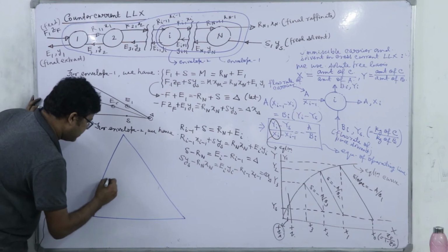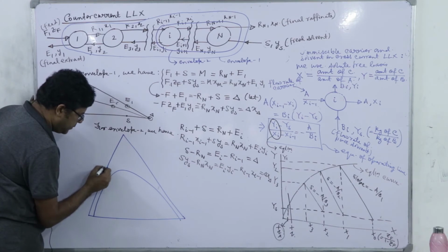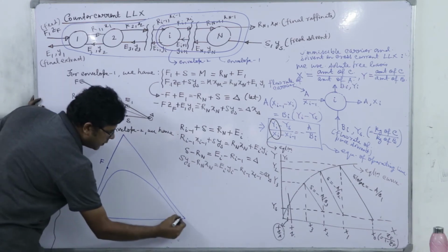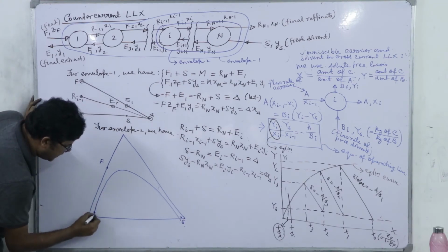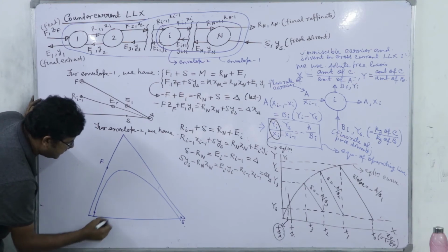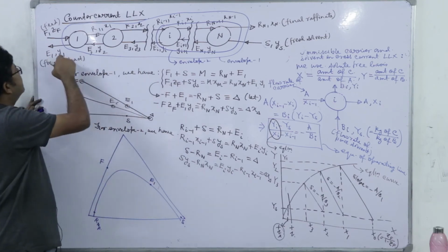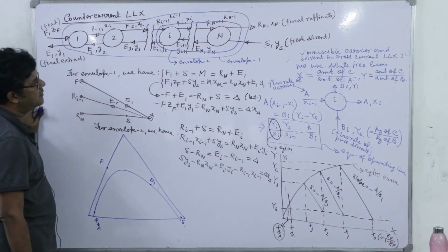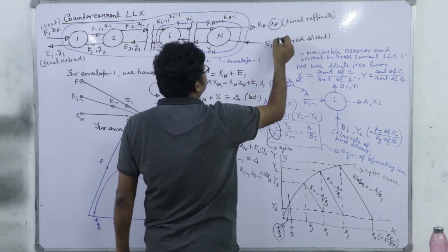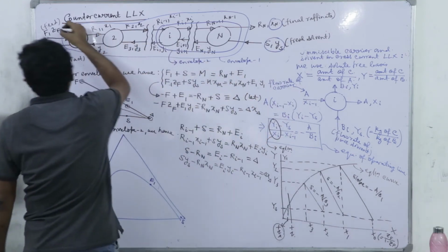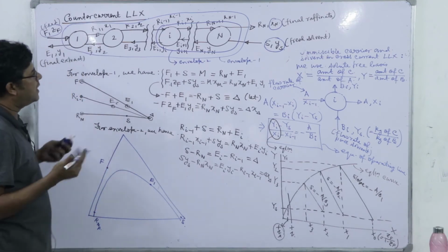So this is the solubility curve. Here I have located the point F, we have located point S, we have located point RNP, and we have located point E1, right? Because this we can obtain from the material balance. As my final raffinate composition will be given, Ys will be given, F ZF will be given, right, and final extract that will also be given.